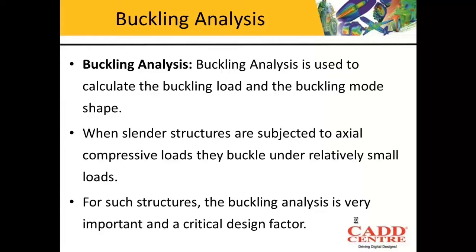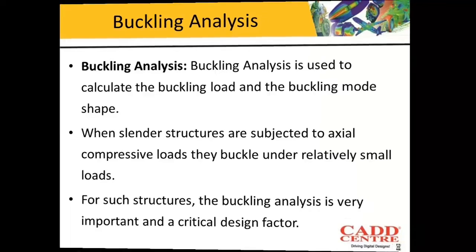When these types of structures are subjected to axial compressive loads, the structure tends to buckle at a certain load value. So in buckling analysis, we have to find out at what load the structure buckles, because it is a very important factor when you want to design. That is what we will be doing in buckling analysis.